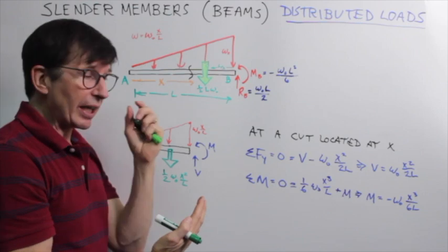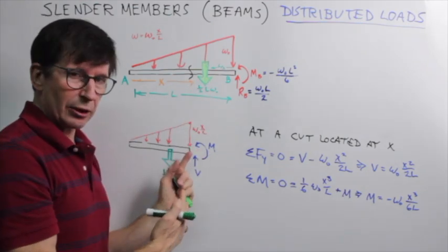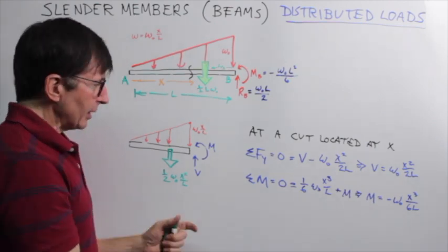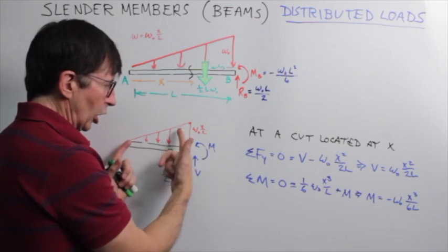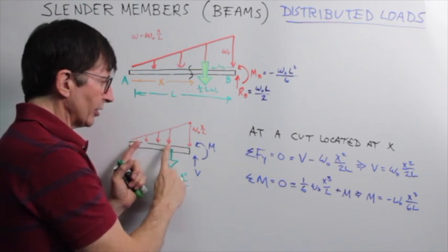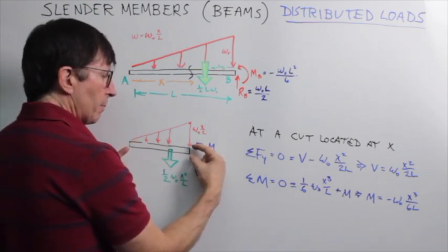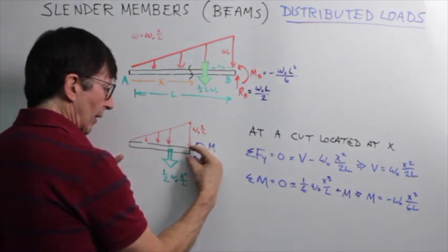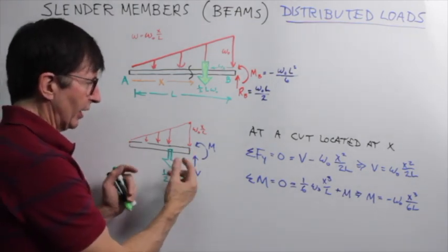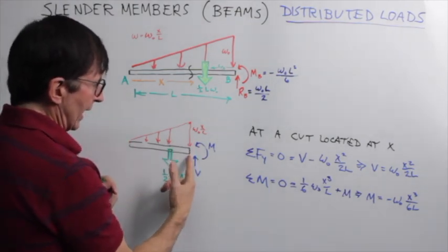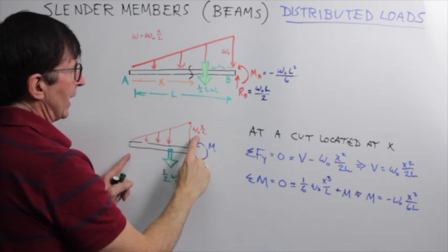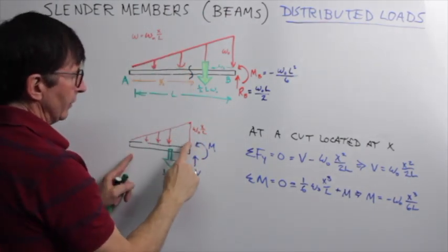So we need to remember that this doesn't apply once we're doing the internal forces and moments, but the principle still applies, because we still have a distributed load, and at this end point, the effect of that triangular distributed load on my putting the equilibrium constraints, like grabbing it with my fingers, can be computed the same way using the resultant of this. So knowing that at any point x by our distribution equation, at a point L, the right end is just W naught x over L.